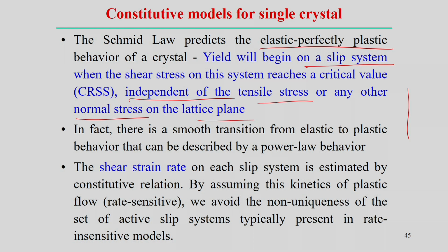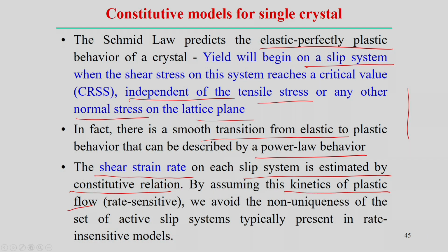can be smooth also. So when you look into the smooth transition from elastic to plastic behavior, then we can look into the power law behavior. We can represent this power law equation, the smooth transition from elastic to plastic. Of course, in that case another parameter can also influence, that is the shear strain rate. So the strain rate in the slip system is estimated by the constitutive relation. But of course the kinematics of the plastic flow can be